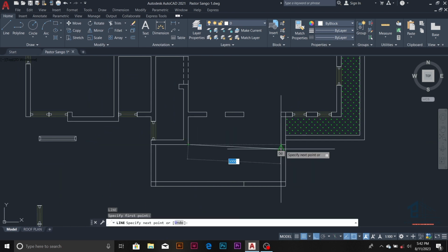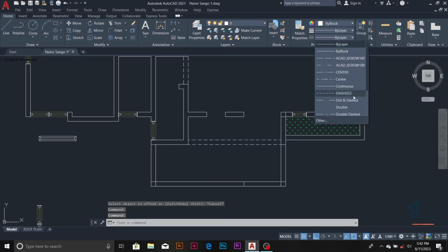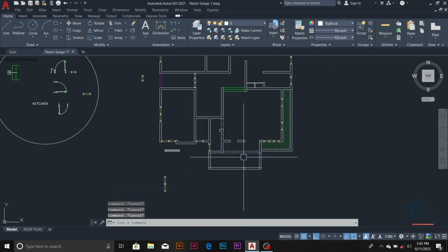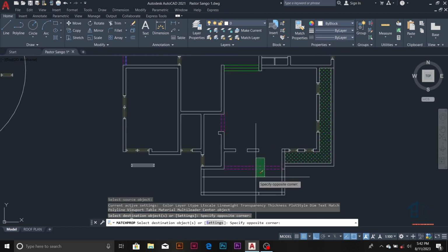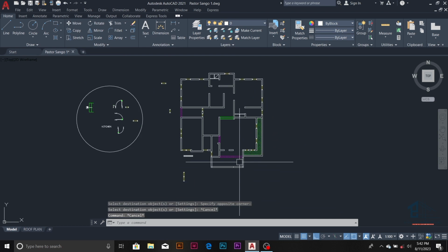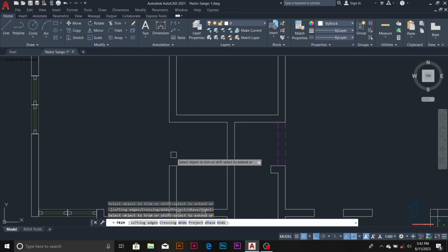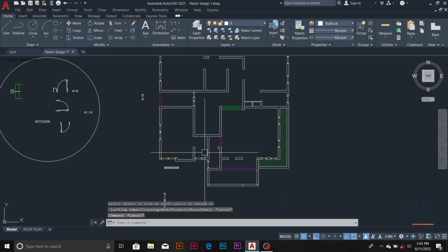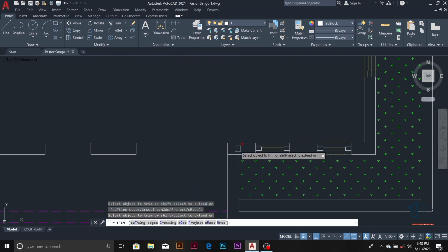There's small arc here. Offset 150. So just come here, put this dot, change it to this color. Let me use on my arc. Let me copy this color. Match, that is match property. There's door here. Offset 900. Yes, extend, trim it, CR.